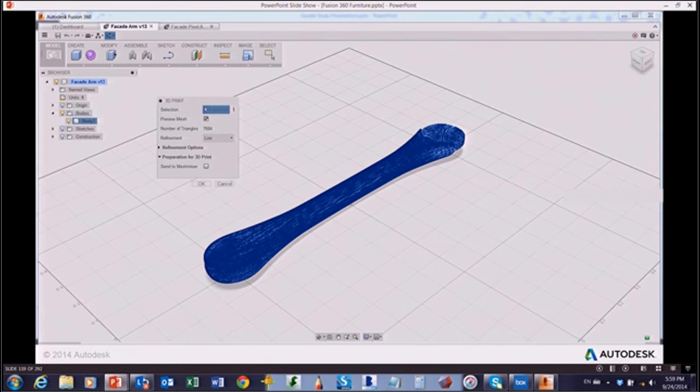The first thing I 3D printed about 6 years ago was a huge concrete panel for a building. And it had this beautiful curve in it. I sent my model to the fabricator. They, as fabricators do, took my model literally. They CNC'd it out, poured the concrete in. Client was there, big unveiling, huge crane, lifted up my concrete panel, unveiled it, and the whole darn thing was faceted. Looked really cool in a really bad way. It was like face, face, face, face, instead of the smooth curve I wanted.